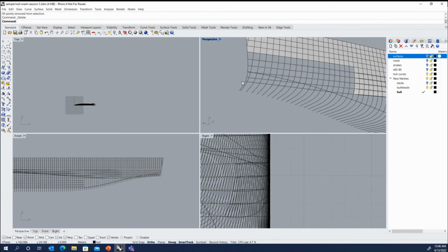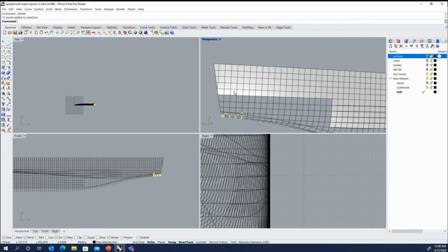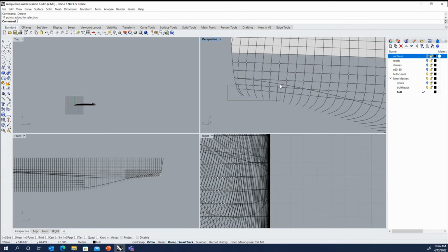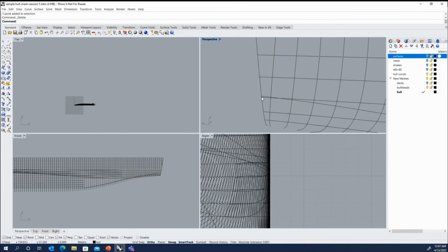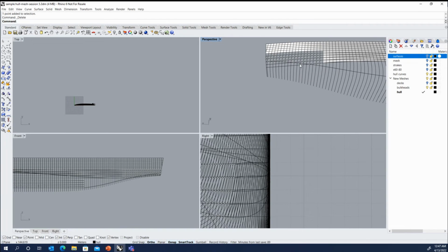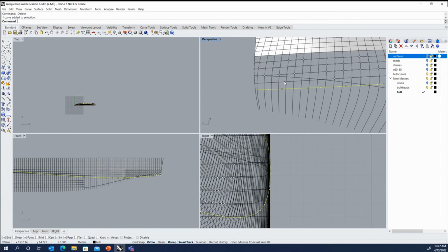And we will delete the points that are below the curve, since we don't want those included in our mesh here. We can leave those in there. Those will be part of the side. Now, when we create similar curves on the bottom, we don't necessarily have to come up and meet. We could use the fill hole command for the mesh to fill in any small gaps in here, or we can create all of our points and then generate the mesh later.